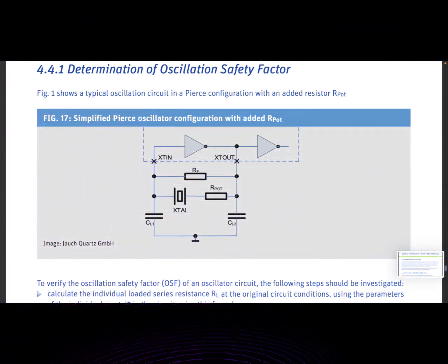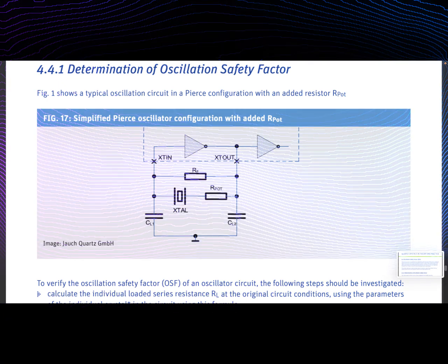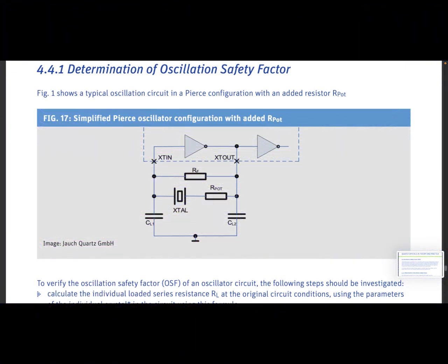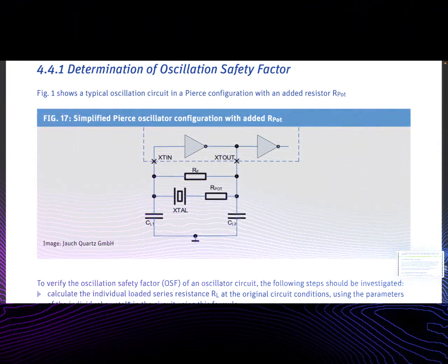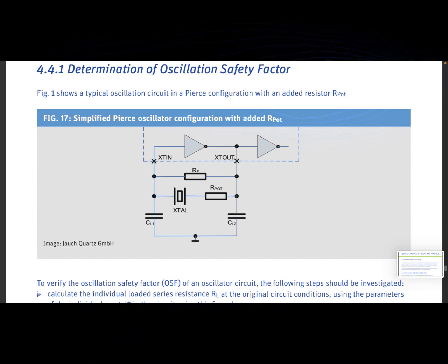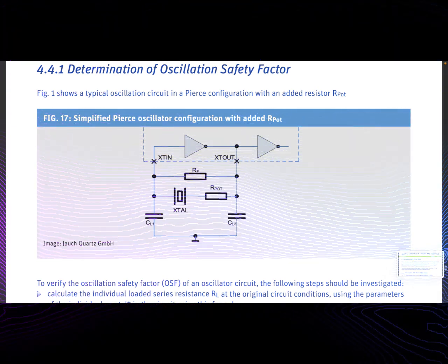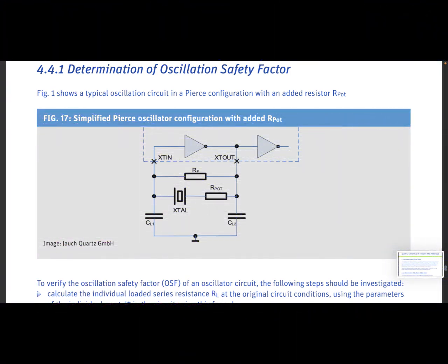Modes of vibration, cuts, and frequency ranges. Resonant mode. The AT cut crystal resonator uses a thickness shear mode of vibration. The following image shows the thickness shear mode of an AT cut crystal. A standing wave builds up inside the crystal blank by reflection at both major surfaces.